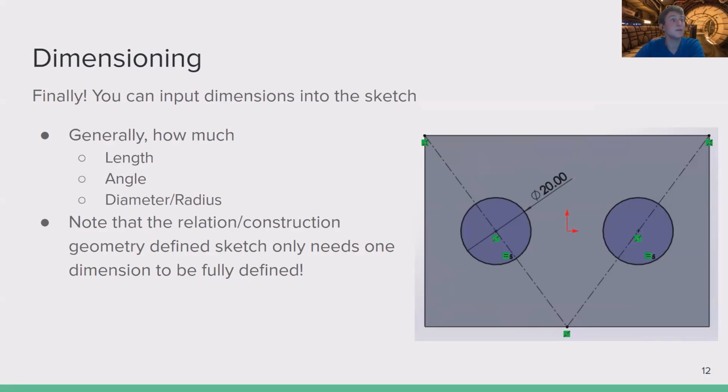It won't move around. It's exactly the size it's going to be, and your features all the way there. If you don't have that, the computer will just put in whatever dimensions it does, so your design isn't necessarily what you actually intend it to be. And also it can do some wonky things. If you have features that aren't fully defined, sometimes you'll grab your part and it'll accidentally extrude something more than you want. You really want to always define your sketches fully so that you don't run into any issues with that. We don't like blue lines here.